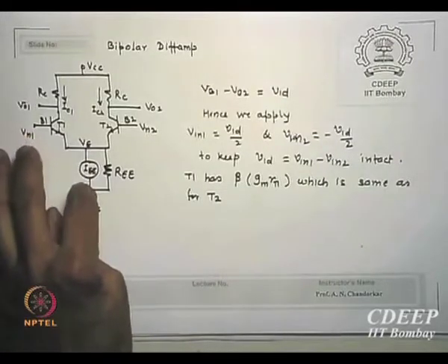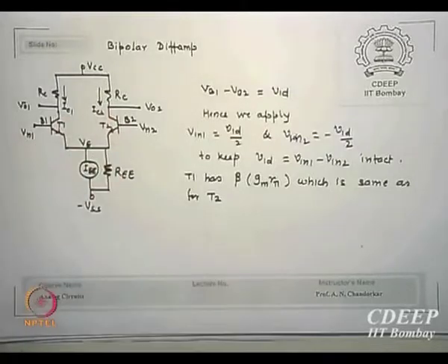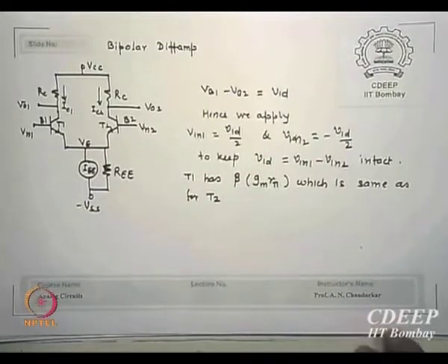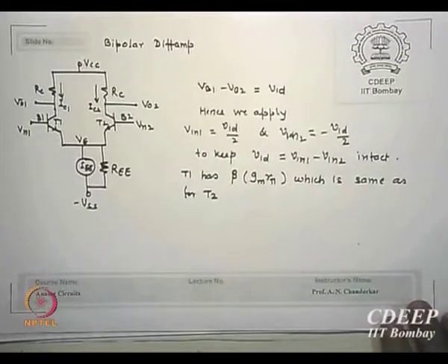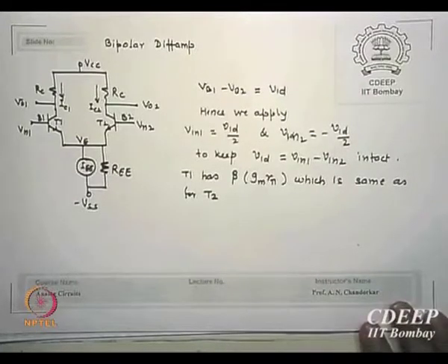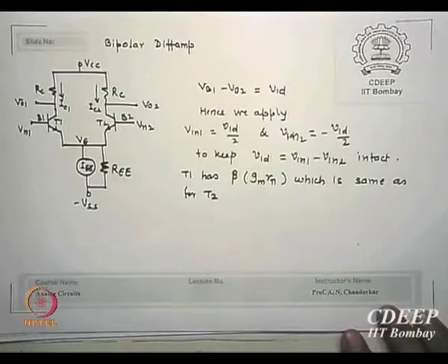Here also there is a current source IE, across it a resistance REE, this is the emitter. In the equivalent circuit we will build, there is a resistance RE we mentioned, small re or RS as it is called, emitter to substrate. That is normally used in many books, but that is around less than 10 ohms or 5 ohms in actual calculations. So if you don't use that, it's much easier to solve.